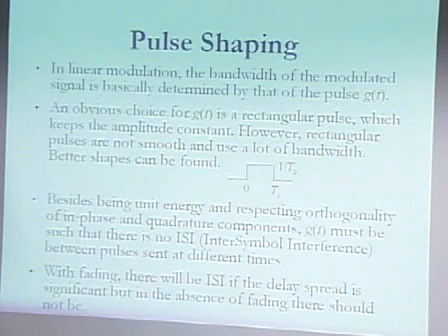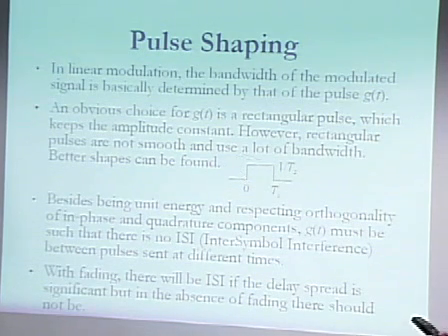Well, okay, I already told you here, so there's no point in asking you. The reason that this is bad is because it uses up a lot of bandwidth. Does any of you have an idea why this shape uses up a lot of bandwidth? If some of you have worked a lot with Fourier transformations before, maybe you can think about properties of the Fourier transformation. Yeah, that's a sin x over x function, exactly, which is a pretty wide function.